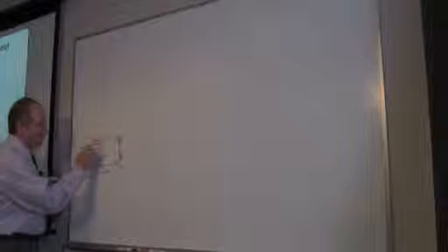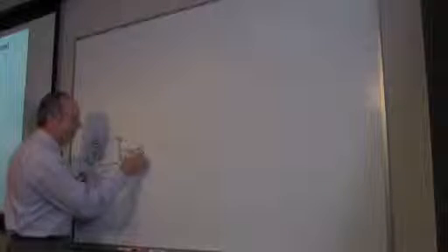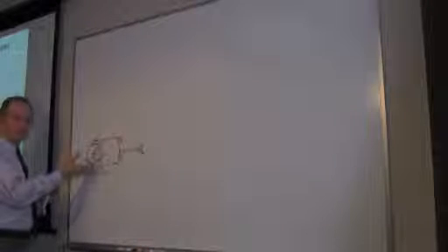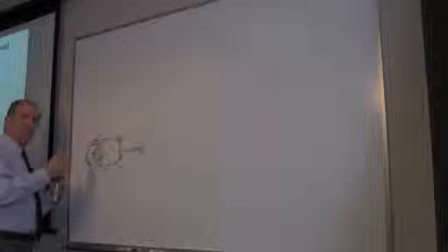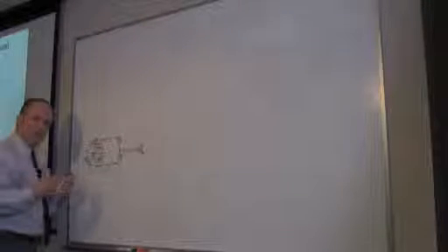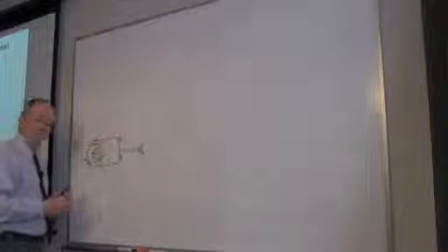In the center, we're going to have the rotor. The rotor is providing the north and south pole. It has a north pole, south pole, and then there's a shaft to it. That shaft is going to come out here, and we're going to spin that shaft. But if this were a permanent magnet and I spun this shaft, I'd be generating electricity right now. But in the power systems, in the big generators, we don't use permanent magnets, we use electromagnets, which means we're going to have a coil of wire.